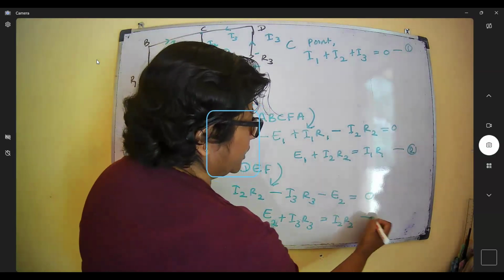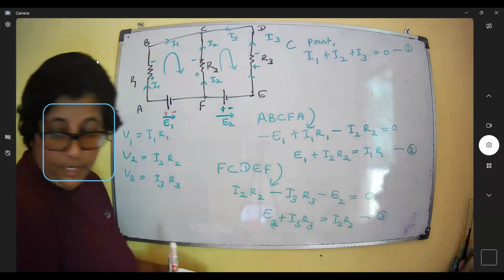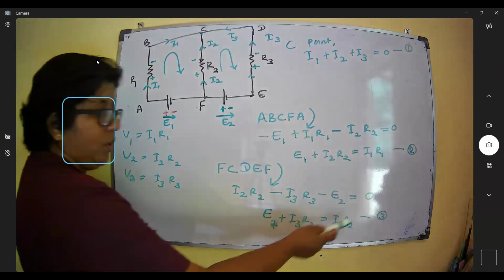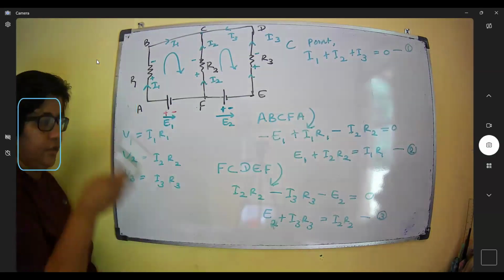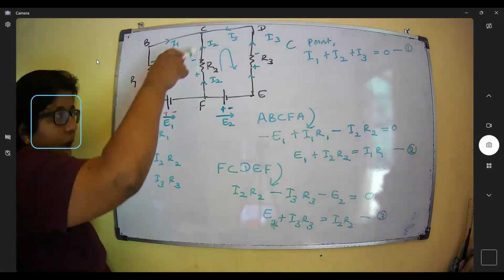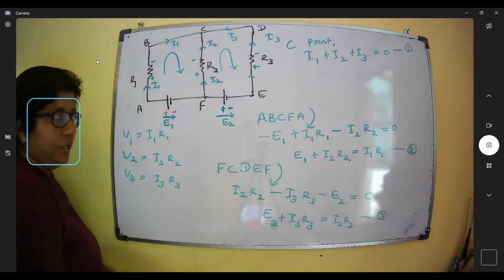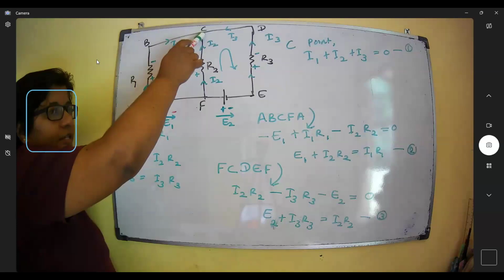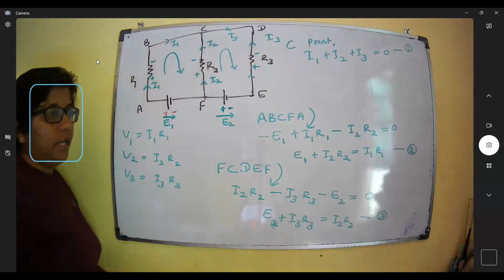Then we have 3 simultaneous equations. You can find the values of I2, I3 and I1, right? Then you should remember, please put positive and negative terminals. Mark all the positive and negative terminals. Then it is easy to handle, right? The first equation is entering current equals 0.